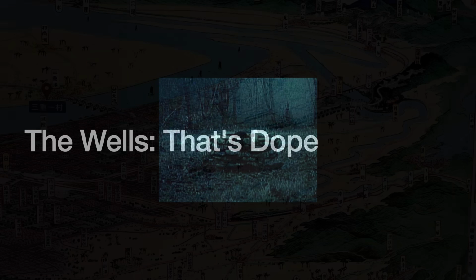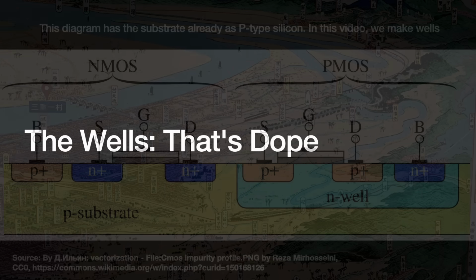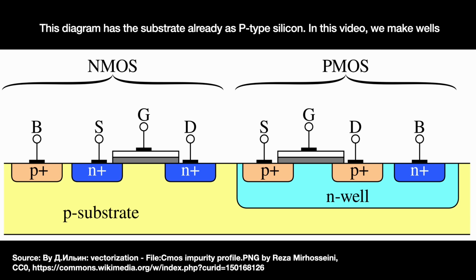Doing CMOS means creating two different but complementary types of transistors on top of the same silicon substrate. This begins with creating special regions on the silicon with doping. These doped regions on which we build our NMOS and PMOS transistors are called wells, or tubs.